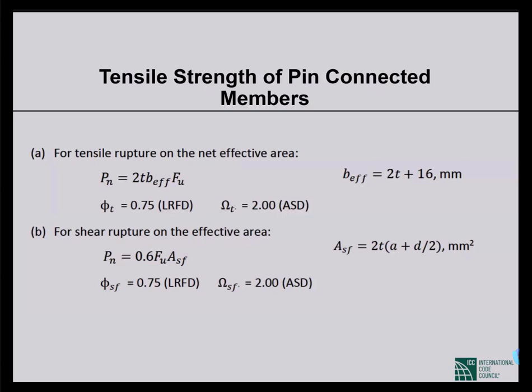But when there is shear along with axial force, it is a three-dimensional arrangement of stresses, and we cannot define yield stress the way we do in the stress-strain relationship of the one-dimensional case. In three-dimensional cases, we talk about the von Mises failure criterion, von Mises stress.